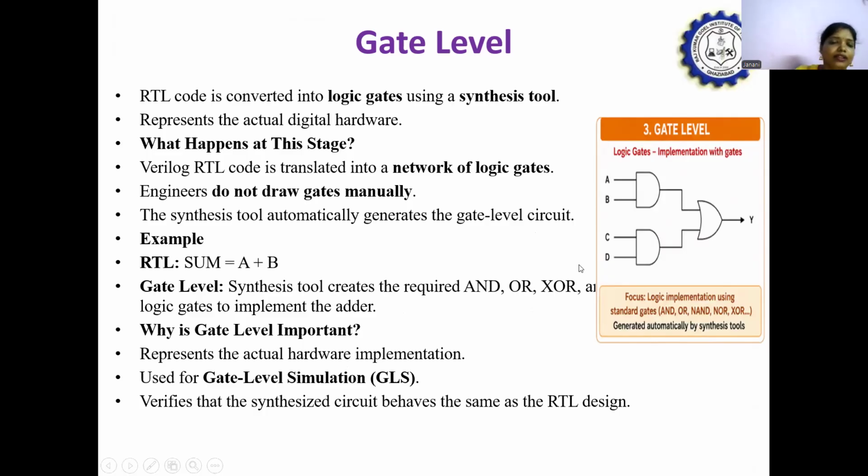Why is the gate level very important? Because at this level we draw the actual digital logic diagram. At this stage we also use gate level simulation to verify whether the synthesized circuit behaves the same as the RTL design or not. Here we also perform verification.